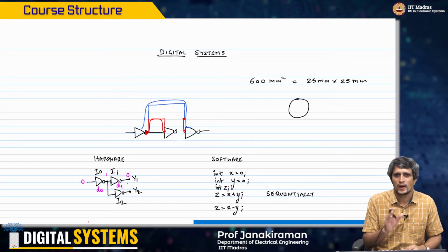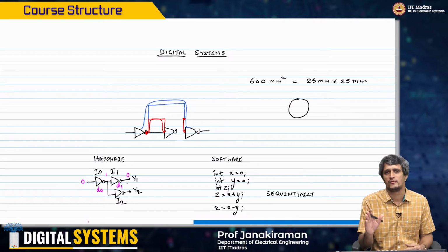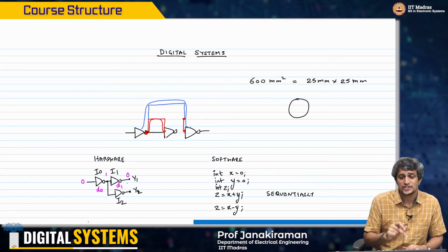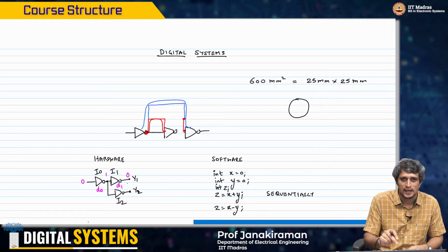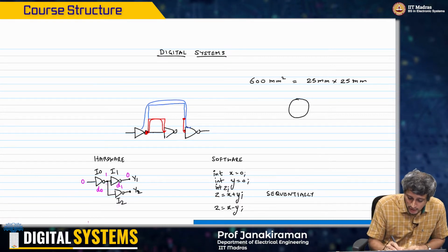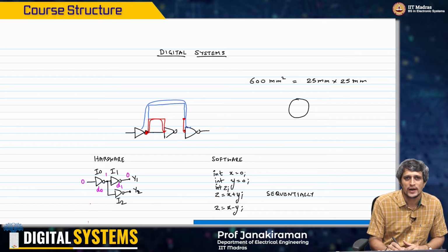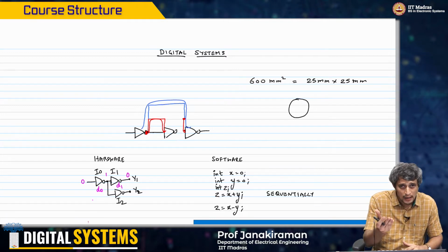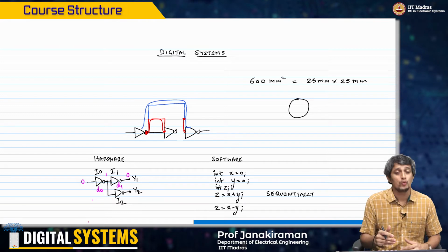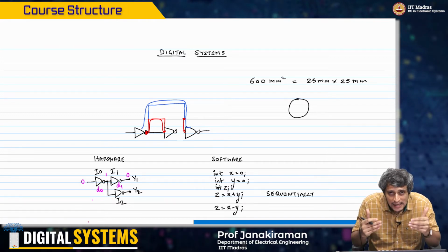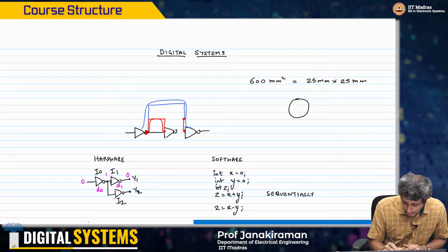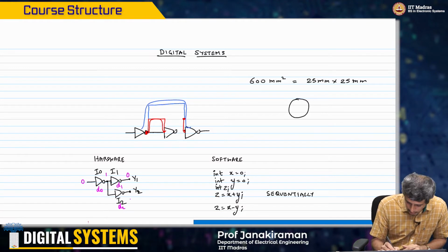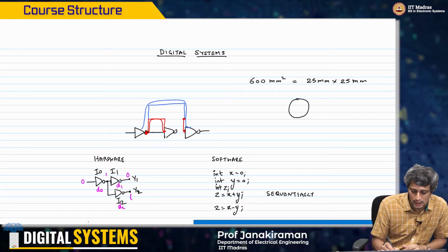Logically Y1 is the same as the input because you have done two inversions. Now at what point will the output Y2 be ready? As soon as I0 evaluates and the output goes to 1, inverter I2 acts in parallel with I1, and therefore after delay D2 itself this output goes to 0.